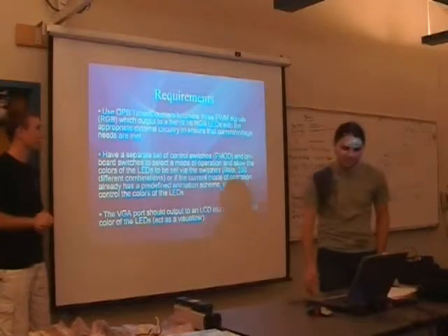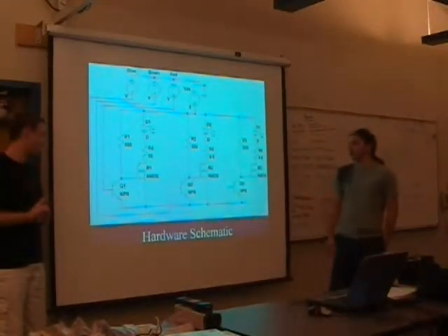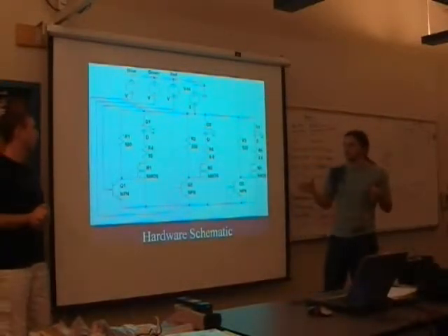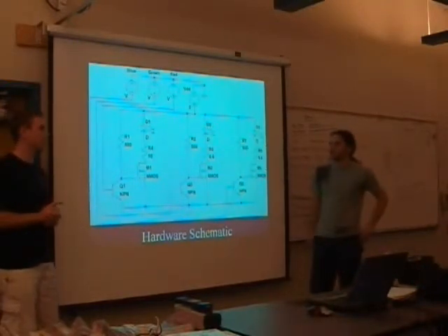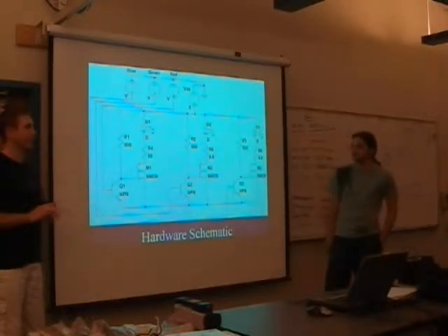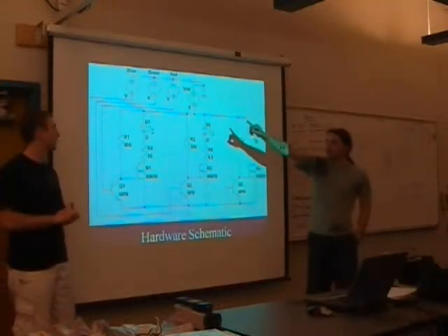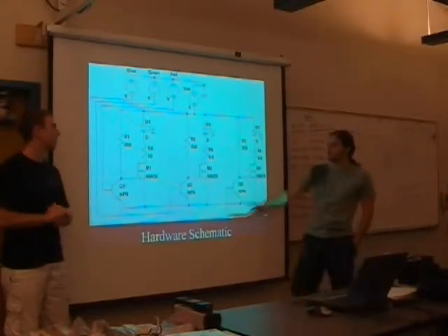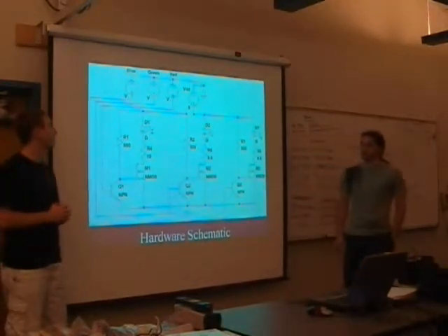We probably don't have time to demo it all, but this is the basic circuit diagram. Where you see these LEDs, there's actually 32 in parallel for each of these, but this gives you the idea, so this one is a single LED. The power supply right here is an external 5 volt power supply, and these 3 signals are the pulse width modulated signals coming from the Nexus board.